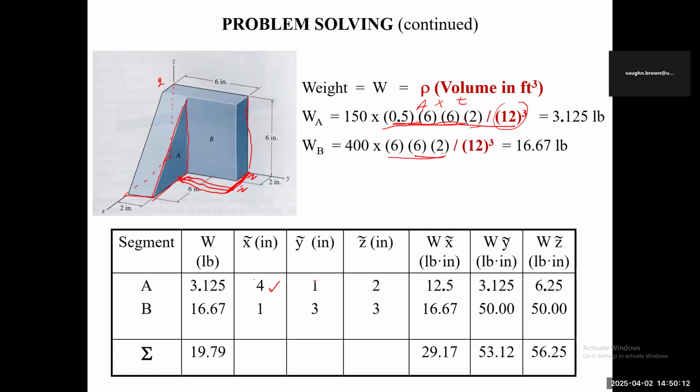And then now for y bar, anybody want to tell me? The 2 at the side there, this 2 here, and half of that. And for the z, the z is going up. What's the height of the z? 6. So it's 1/3 of the 6, which gives you 2. So it's 2 from the origin for that face. So the height for z is 2.